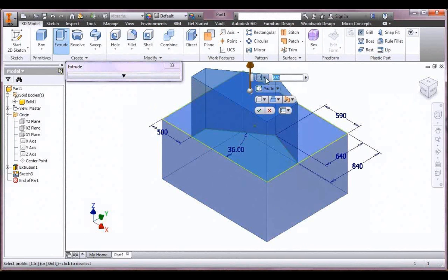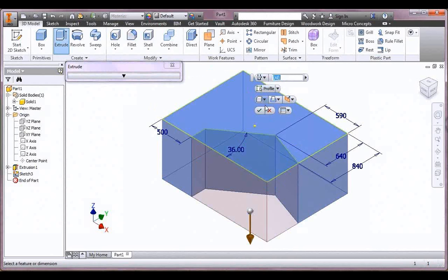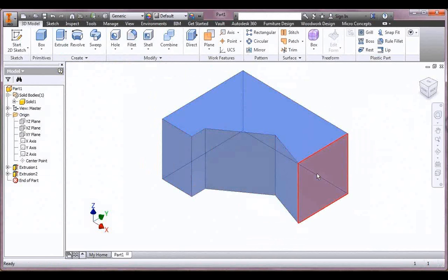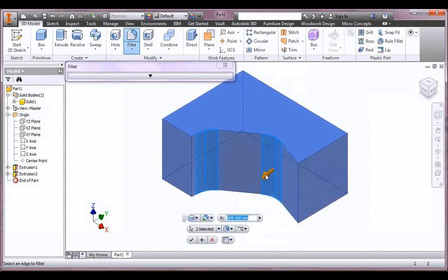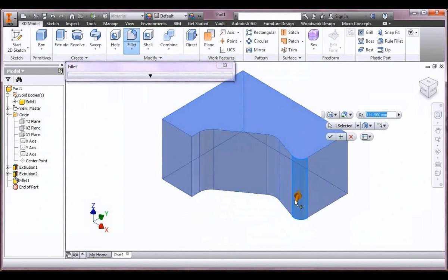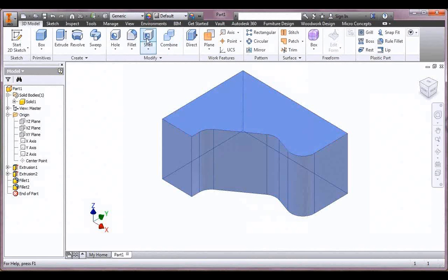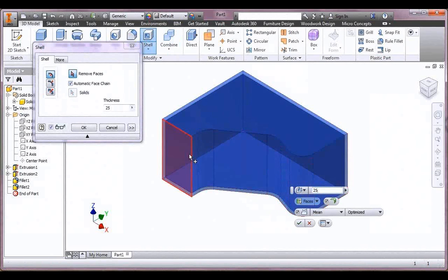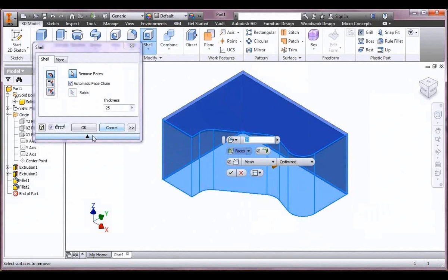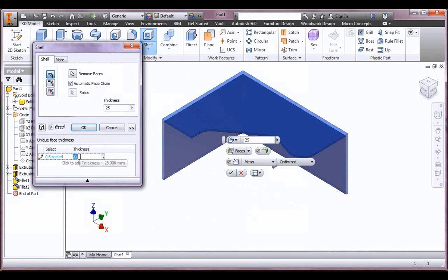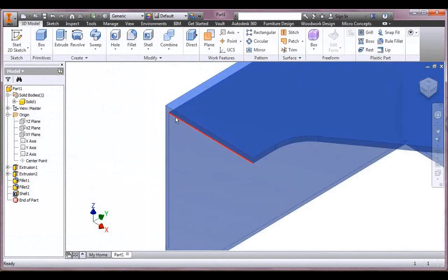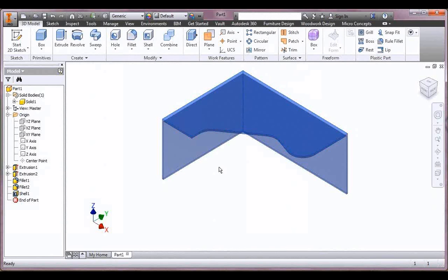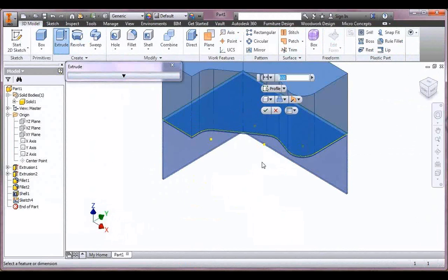Again, with the heads-up display, you can choose maybe a cut. We just say we want to move that extrusion through all, and it automatically knows it needs to do a cut. We've got some other cool tools on here, such as fillet. We just put in a variable, and by dragging the direction indicator, it's easy to change. I'm just using a technique now to remove some material, and I've used a different thickness. What I need is 18mm panels for the back, but I want the worktop to be physically 25. So I've got two material thicknesses there, but it's still one part at this stage. This is just one approach to modelling.